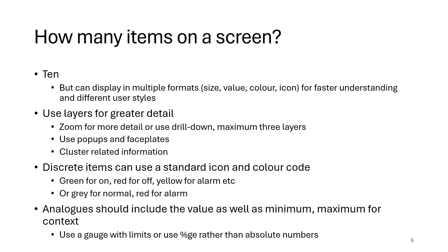Another aspect possibly is also thinking about color blindness. So it's important that the colors contrast quite well, rather than what the actual colors are. But certainly with some men, green and sort of brown color blindness is common. Green and red can also be an issue. And then there are other levels of color blindness as well. So just check with your operators that they can actually see and work with the colors that you've chosen.